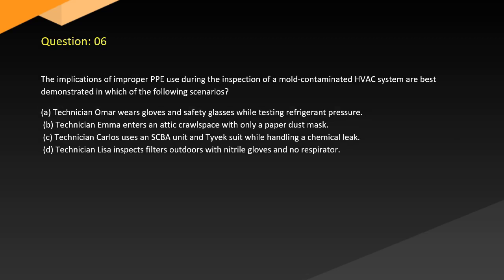Question 6. The implications of improper PPE usage during the inspection of a mold-contaminated HVAC system are best demonstrated in which of the following scenarios? A. Technician Omar wears gloves and safety glasses while testing refrigerant pressure. B. Technician Emma enters an attic crawlspace with only a paper dust mask. C. Technician Carlos uses an SCBA and Tyvek suit while handling a chemical leak. D. Technician Lisa inspects filters outdoors with nitrile gloves and no respirator.